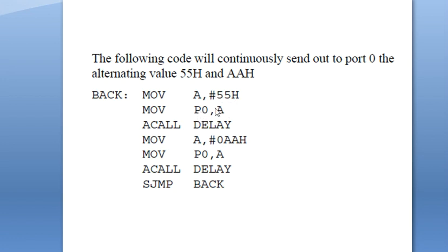So this port is alternately making all its pins on and off. 0 means it is going to be an output port, and 1 means it is going to be an input port. So if you are sending 0, it will be an output port, and 1 means input port. By default, you are making the first pin an output, the next pin an input, the next pin an output, the next pin an input. Like this, alternately you are making output and input.